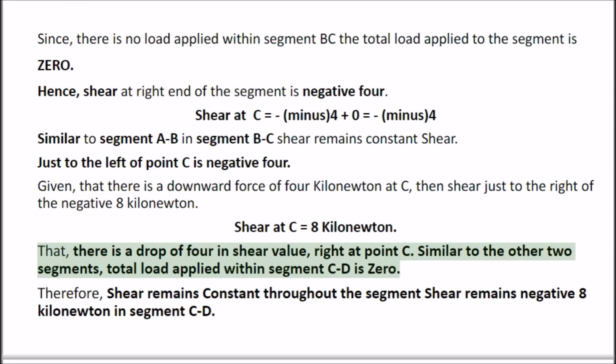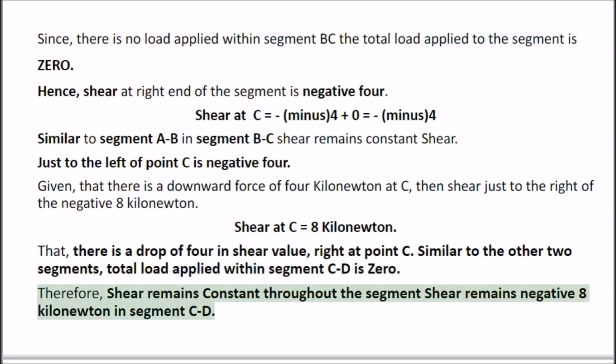Similar to the other two segments, the total load applied within segment CD is 0. Therefore, shear remains constant throughout the segment. Shear remains -8 kN in segment CD.